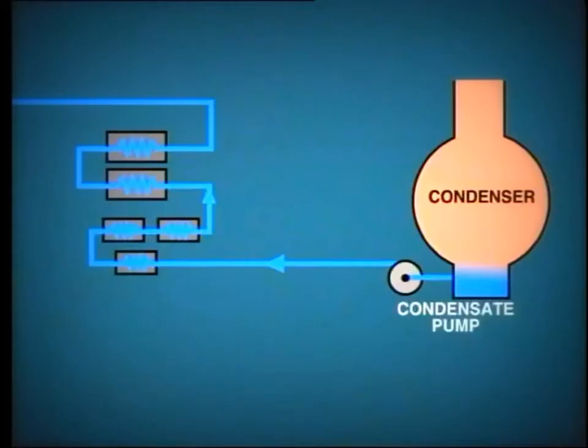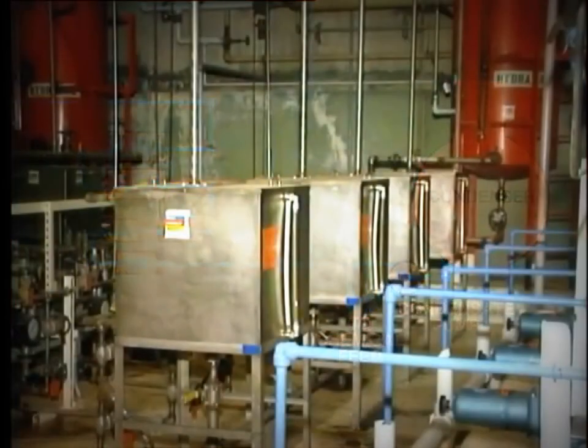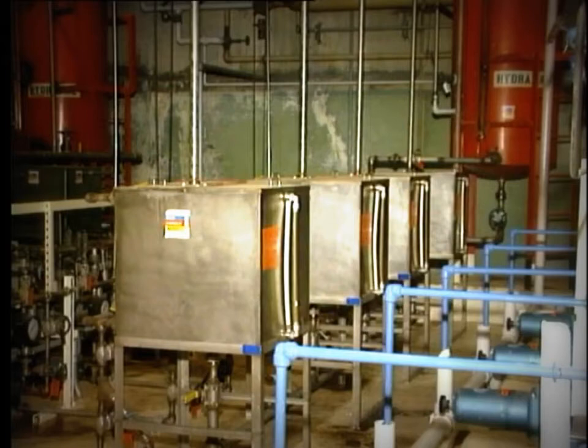When you walk around your own condensate system, you'll notice a large number of connections to various pieces of equipment. Let's look at a typical arrangement. Soon after the condensate pumps, we notice small piping connections to the chemical feed system. This allows us to fill the chemical feed tanks and mix additives such as morpholine, hydrazine, cyclohexylamine, and other products for subsequent injection into the condensate system.